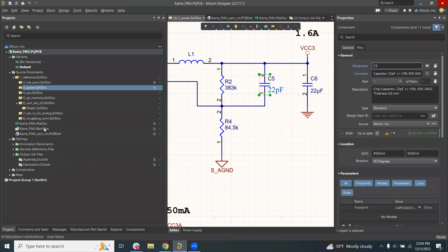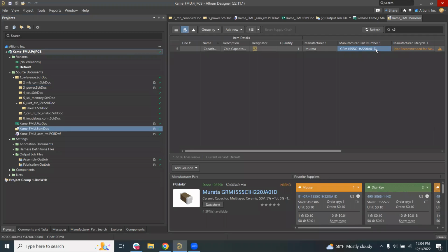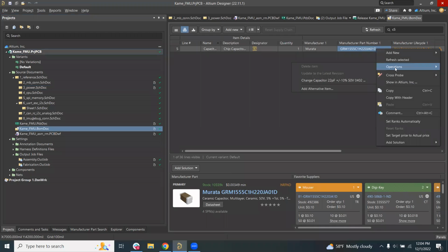When I opened up the BOM dock, I searched on that component as well, so I could actually see that it was truly up to date from the operations. Notice that it isn't available to be pushed to the latest revision anymore because I've already made that change. But this is where, when the other person was asking how can I choose an alternate item, it's going to be within the Altium Designer through the BOM dock. And that's why those comments are really invaluable, because I know immediately what component someone's already reviewed. They're sharing with me, you know, Christine, go and choose a different alternate item, and I can go ahead and do so.